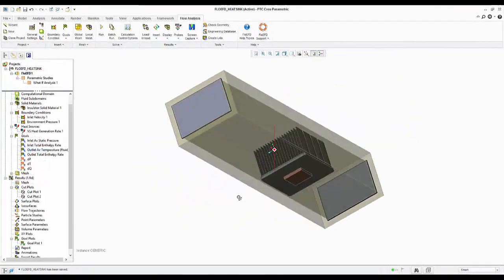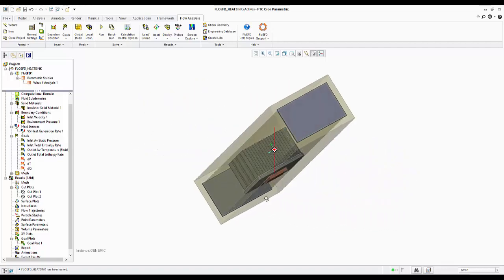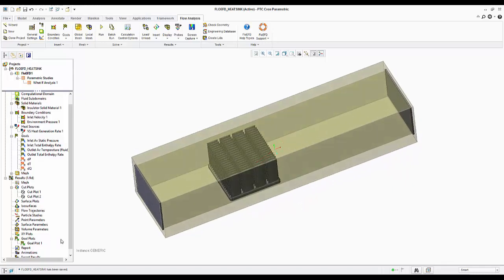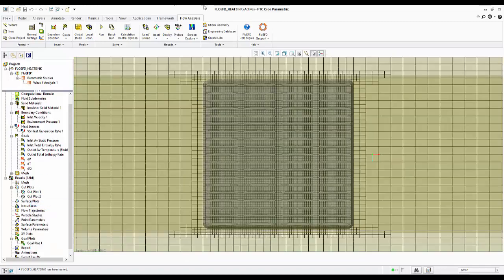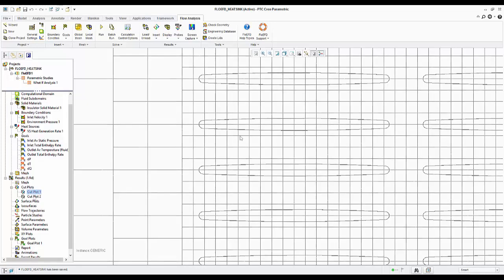The third key technology is how FloEFD handles the boundary layer which forms on the surface of a solid. This example is using a heatsink in a wind tunnel to determine thermal resistance and pressure drop characteristics. Looking at the mesh shows the Cartesian nature again with finer grid levels around the heatsink fins. Multi-control volume cells exist at the walls, which is where the proprietary wall function is applied. This allows for coarse meshing at the walls whilst retaining the correct flow and heat transfer characteristics.